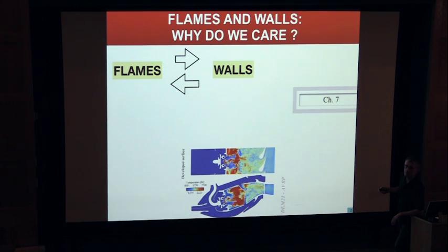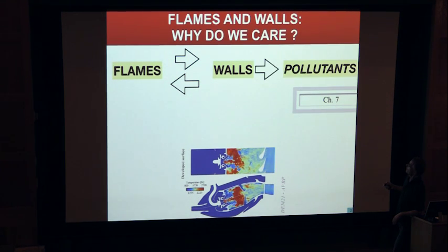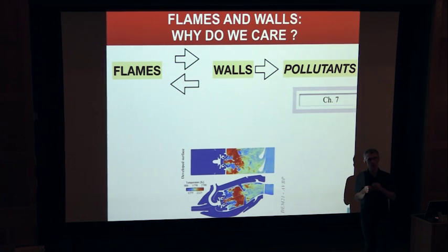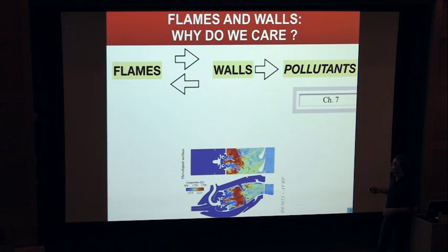Why do you care? You care not only because the flames will touch the walls. You care because the walls will affect the flames. I will describe that in a second. And the walls will also control pollution, because if the flames get quenched near the wall, that means you will leave some unburned hydrocarbons near the wall, and these unburned hydrocarbons can then leave and go into the exhaust gases in a piston engine, for example.